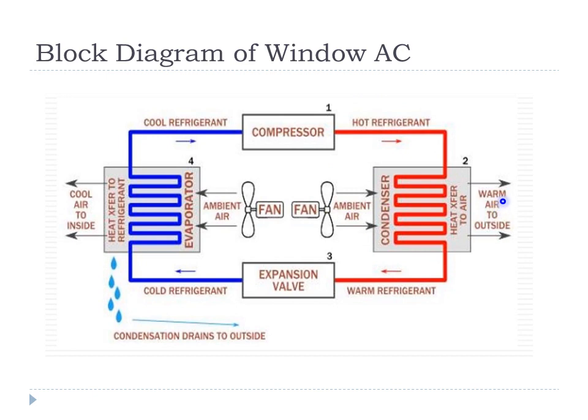You can see how warm air is coming out of the condenser, and how we use this fan to get ambient air flow over the condenser surface. We also see that evaporator coils are here, from which we get cold air channelized back into the room, and thus we get conditioned air.